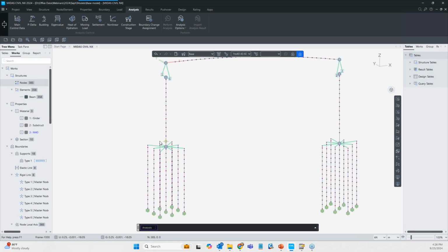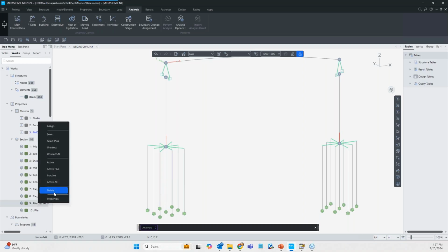So this is a cap element. You can see this particular section and pile cap section. This pile cap section is created as an element, as well as the rigid link, from the plugin, and the piles with a number of divisions and the support below that. So it's assuming it as an end bearing, but again there is a plugin coming with the soil spring application as well, so that we can expect in the future.